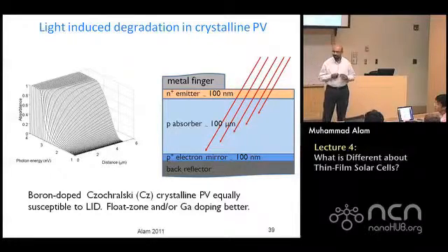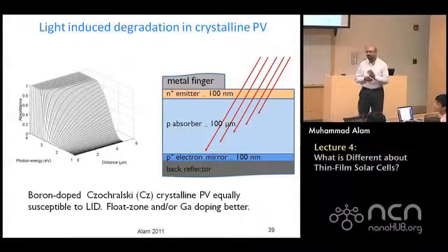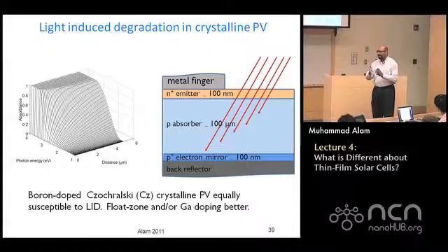Yeah, I think if you do numerical simulation, many features of it will show up, because you cannot really separate out the recombination and the injection over the barrier into separate components and add them. Because at every point, just like the transmission picture shows, you have a probability of recombination and a probability of going up or down in the barrier. So when you add them up, unlike a PN junction, where it's very sharp and small, you expect more complicated n values.